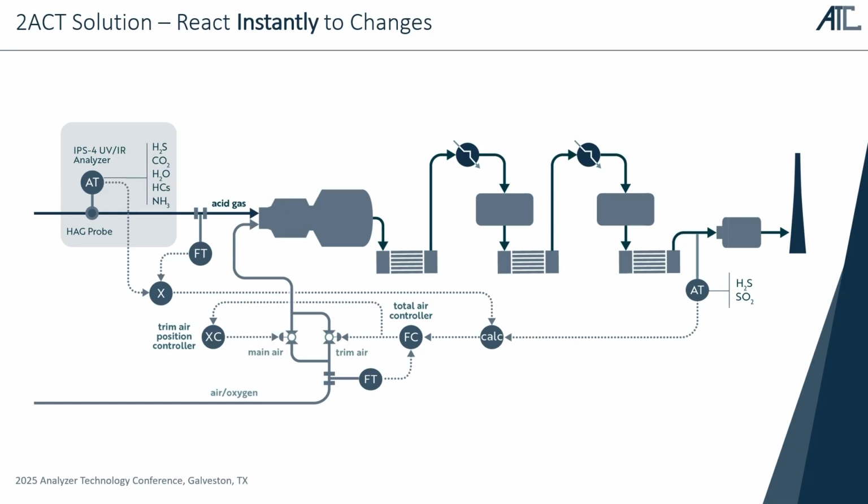That valve is able to respond quickly, but by the nature of the size of the valve, would only be able to control some 10 to 15% of the total air demand, meaning that if the change to the process is big enough, it actually is out of control pretty quick, and then if the valve is fully open or fully closed, you know, you're out of control completely. It's just not doing anything anymore.